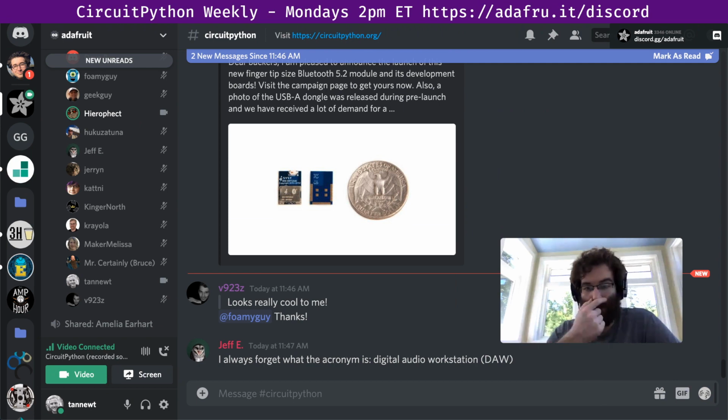Now you can do all sorts of new things with the clocks. You can override the default clock settings with custom clock settings. It's fixed a lot of things that had to do with the low power operation. It's raised the frequency on a lot of dev boards up to their maximum. So in general, it's made that whole section of the STM32 board a lot more stable.